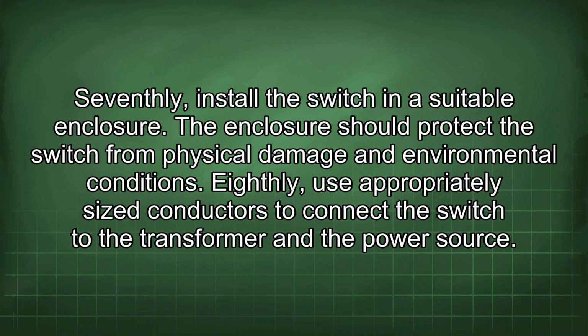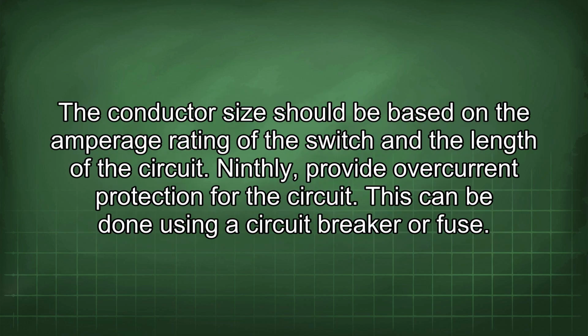Seventhly, install the switch in a suitable enclosure. The enclosure should protect the switch from physical damage and environmental conditions. Eighthly, use appropriately sized conductors to connect the switch to the transformer and the power source. The conductor size should be based on the amperage rating of the switch and the length of the circuit.